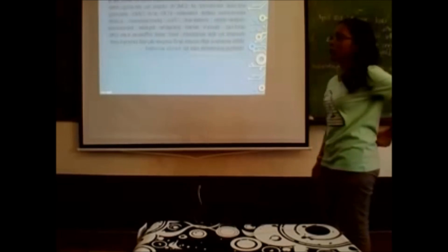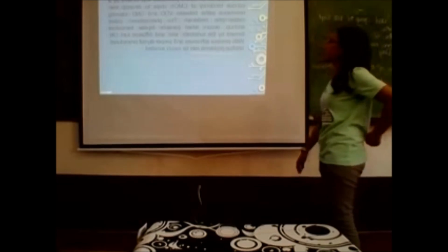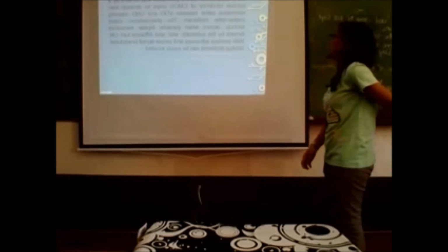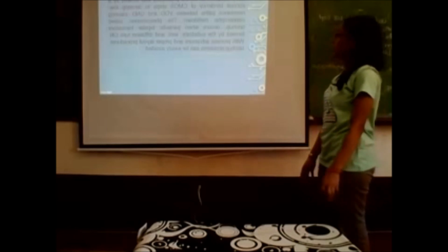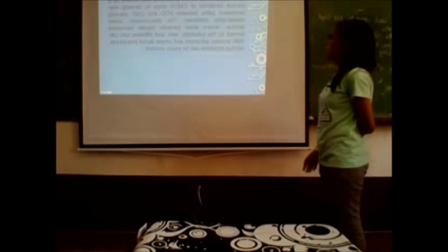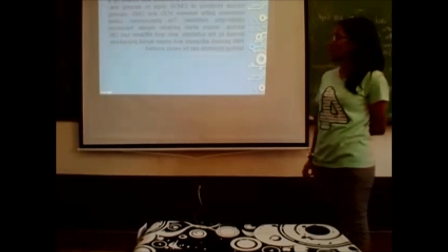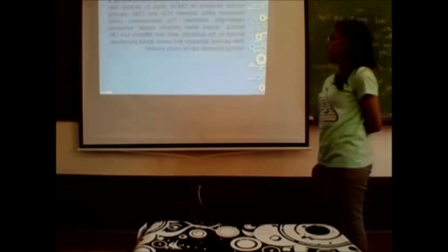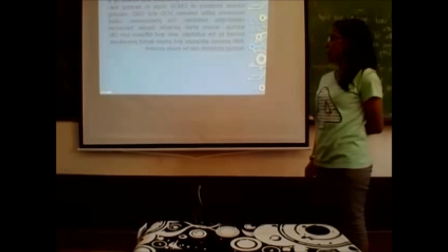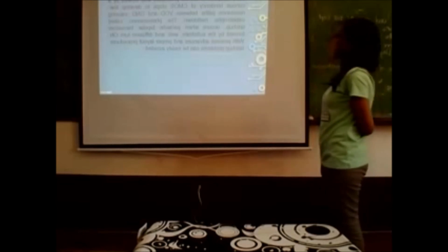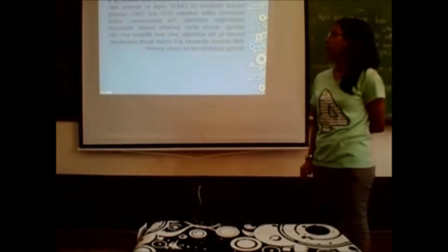Early adoption of CMOS processes was slowed by the tendency of CMOS chips to develop low resistance paths between VDD and ground, causing catastrophic meltdown. The phenomenon, called latch-up, occurs when parasitic bipolar transistors formed by the substrate, well, and diffusion are turned on. With process advances and properly run procedures, latch-up problems can be avoided.